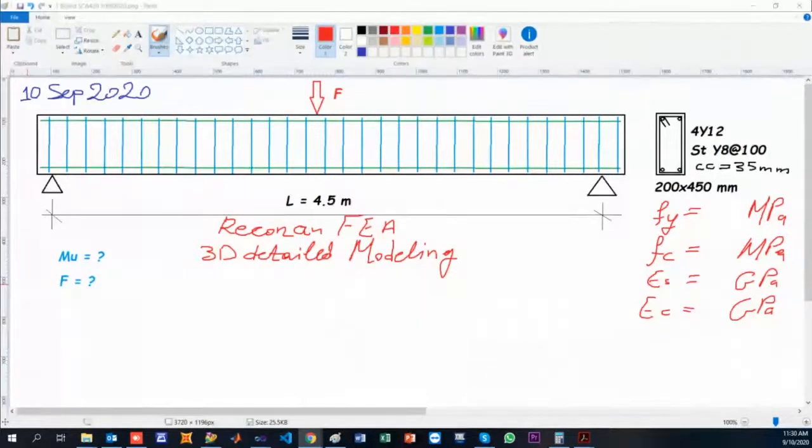Today we're going to have some fun with modeling, and we're going to go all the way by modeling a simply supported reinforced concrete beam that you can see in front of you. The reinforcement ratio and the detailing geometry are provided. I want you just to choose the material, and then we're going to see also modeling of a framing system with 4 columns, drop beams, and shear walls. We'll learn a lot in relation to how reinforcement affects the mechanical behavior of structural members through computer methods, which is our finite element analysis software here.